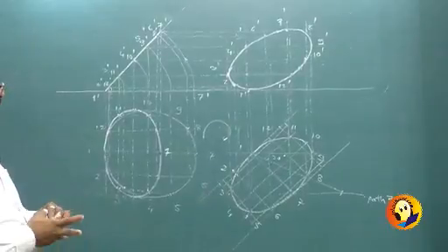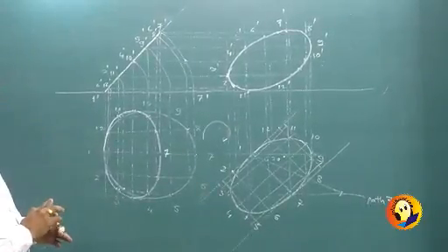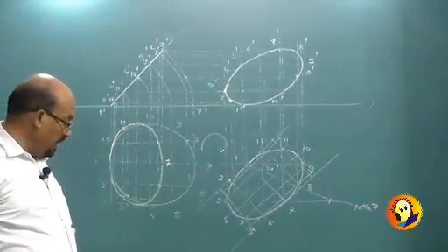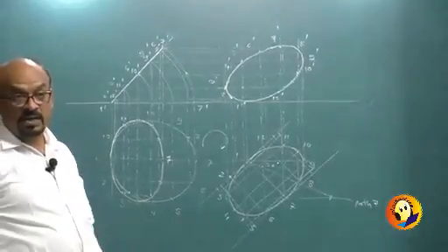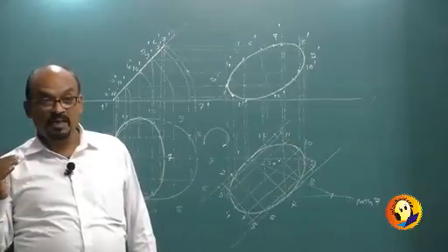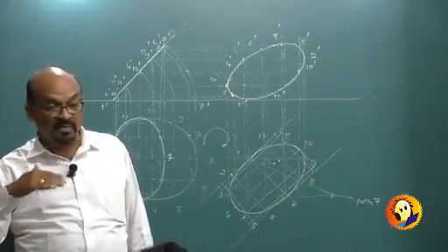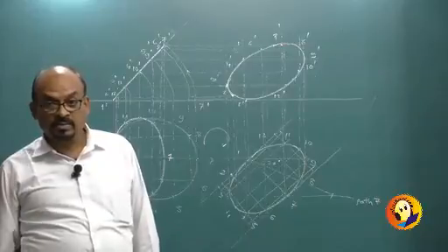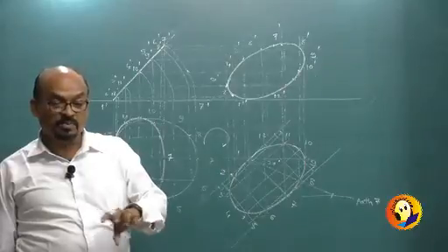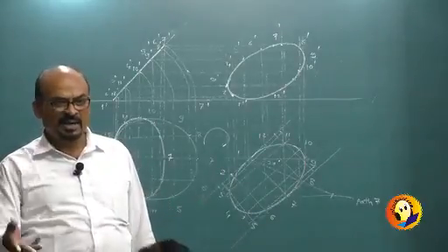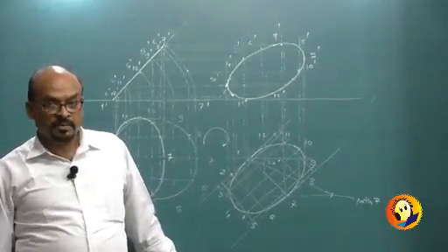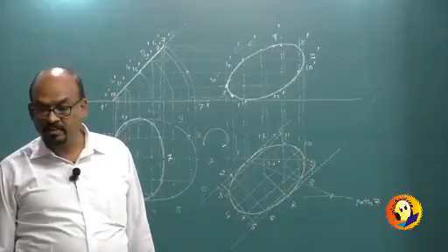The construction should be visible. It's a time consuming problem because 12 points and so many lines. Now here is the skill that you need to use that roller scale very properly, because all the lines should remain parallel. If they move, just change the angle even by half the degree, there will be chaos, right? Do it. If you want, you can take the diameter to be slightly bigger, whatever, but still it is okay. 60, 80 is the, they can ask you in the exam. Okay, do it.